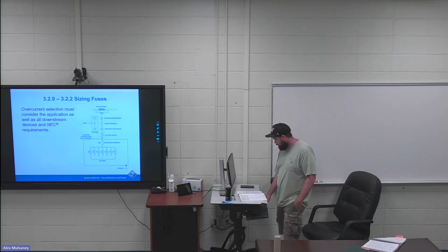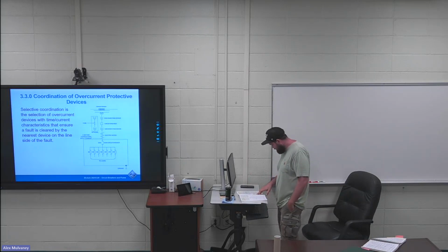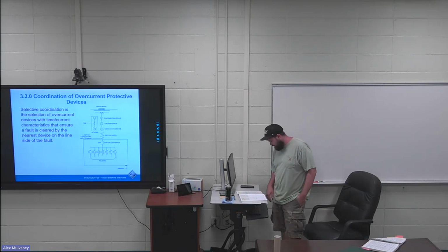330, coordination of overcurrent protective devices. Page 21, 330, first sentence is highlighted. Coordination is the name given to the time current relationship among a number of overcurrent devices connected in series, such as fuses in a main feeder, sub-feeder, or branch circuits.